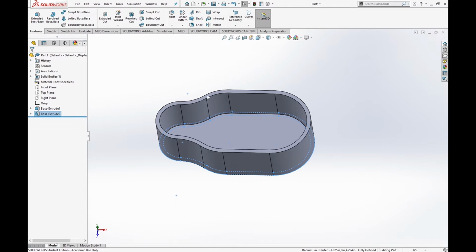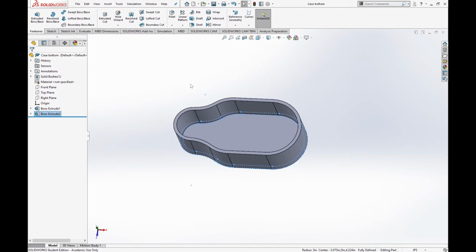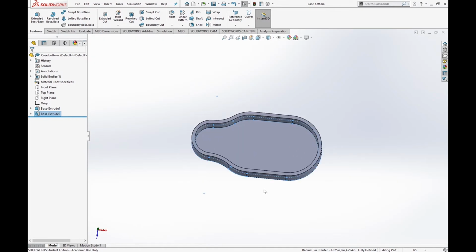And so this is the workings of your case. Once you determine where your frame points are going to be to mount this on your frame, then you can come back in here and extrude some bosses so that you can set where your case is going to bolt onto the frame. And then we're also going to come back in here and create screws so that we can screw on the top case also.